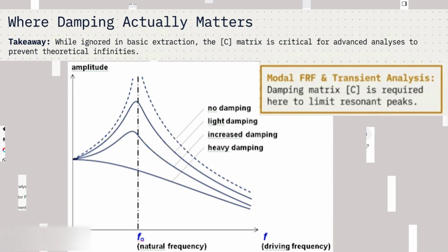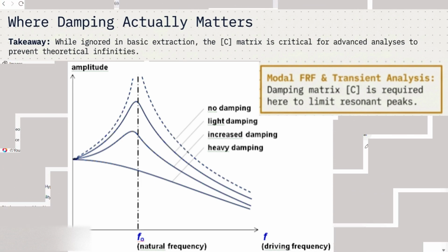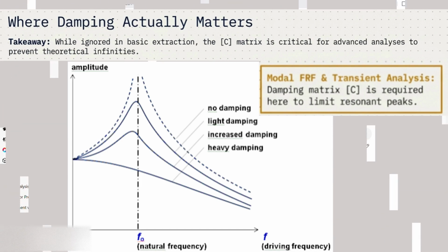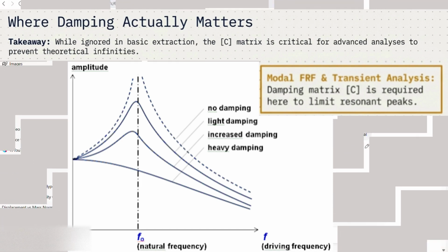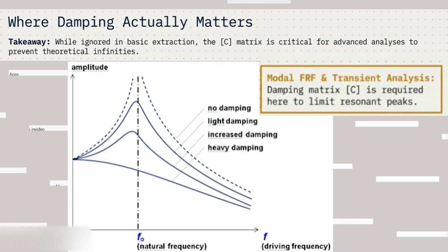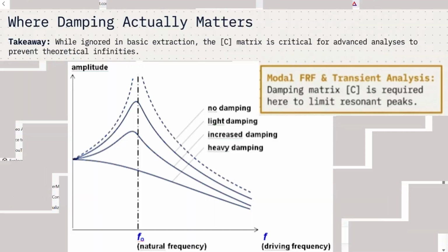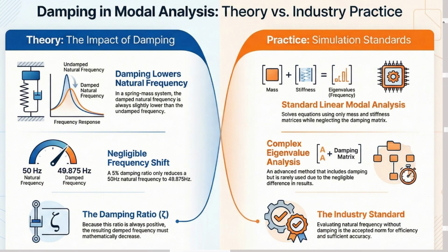Whatever damping is defined here can be used in modal FRF and modal transient analysis, which are somewhat advanced analyses and which we will discuss later in some other video. The standard modal analysis you run doesn't consider the damping effects in the natural frequency.